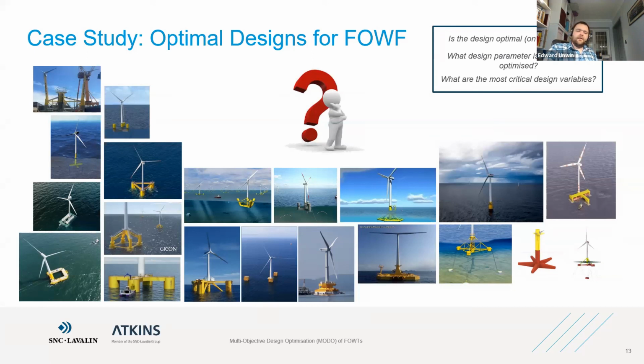Where they aren't able to respond would be at the higher frequency, lower period motions, I suppose wave frequency yaw. They typically can't counter that, and can't really do much about pitch and roll. But for drift frequency yaw, the controllers and the yaw bearing on the nacelle can keep up with that if needs be.